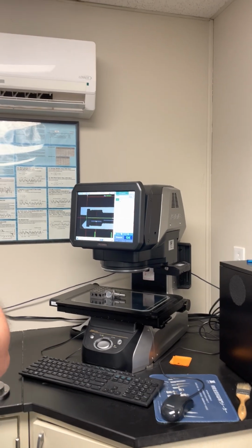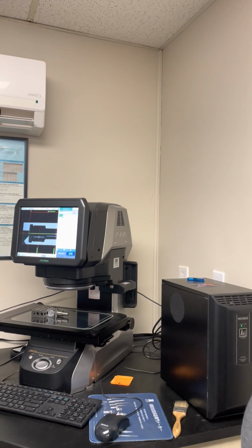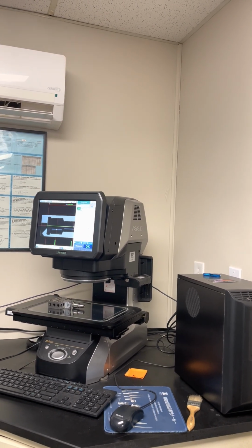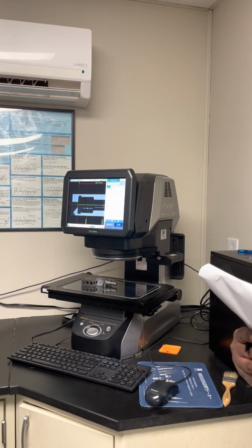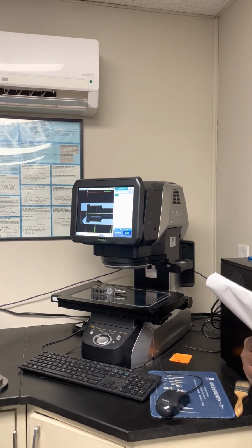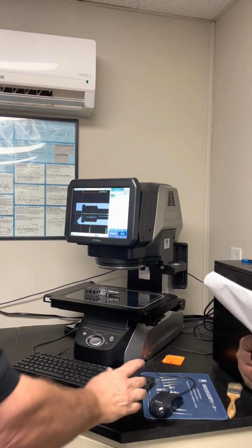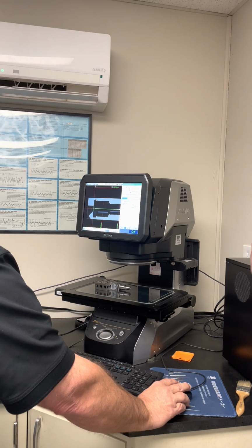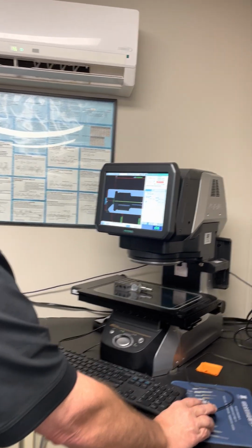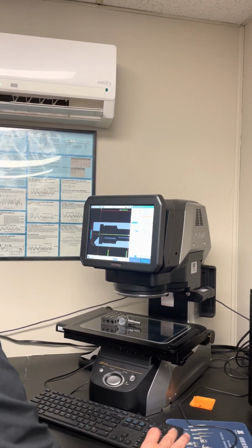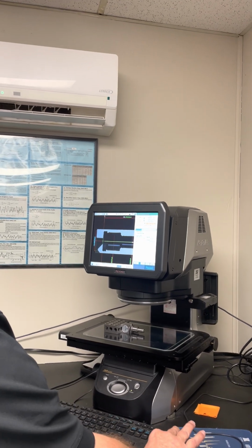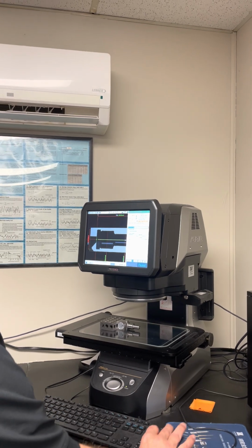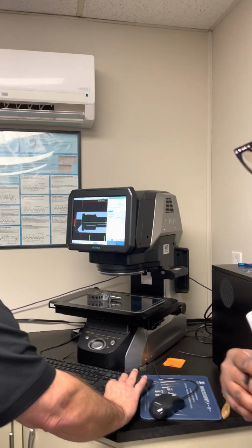The other thing you can do, if you know where that's at, is put a parallel line in there showing that, so we don't go past it as well. Good. How about this diameter here? The head diameter. 0.853 plus 0 minus 0.010.